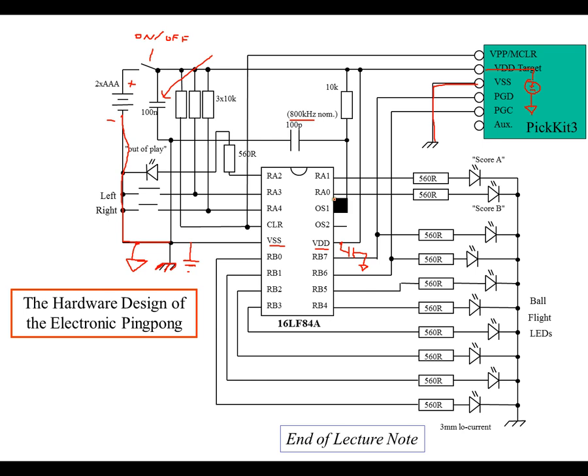Now don't forget, inside the code, you're going to have to set up your configuration word. Okay, so don't forget about your config word. You have to configure it through your PICkit, your MPLAB. Your software is going to allow you to set that configuration word. It's basically going to be just a drop-down menu. You're going to click on this drop-down menu, options or something like that, and look around for a configuration word. We'll talk about that during the next chapter.